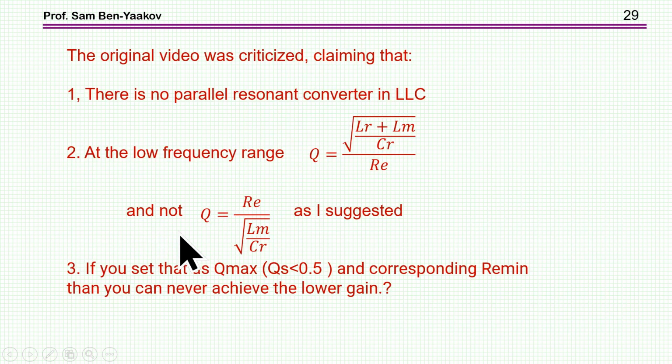So let me go back now to the 3 points that were raised. Number one, that there is no parallel resonant converter in LLC. Well, as I've shown, there is a parallel resonant LLC. In fact, it should be said that it's a parallel loaded resonant converter, and this is what is now accepted in the literature and among the workers in the field.